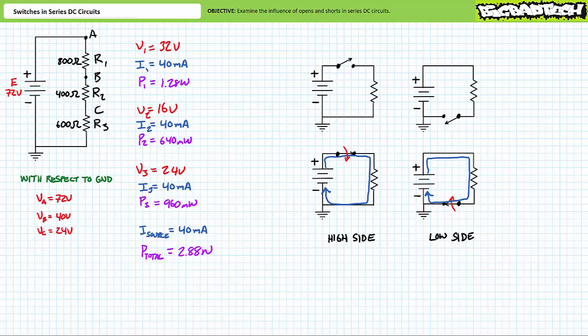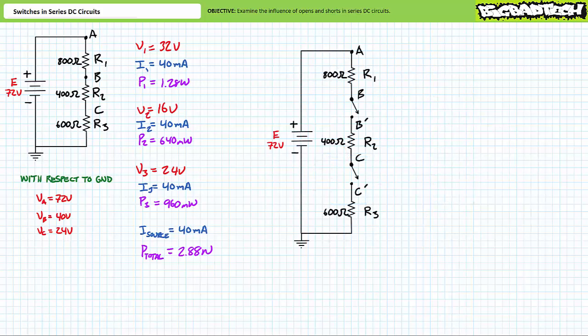I will, however, leave you this clue. Consider an open low-side switch, whereby some errant conductive element accidentally touches the electrical load. What happens? Tune in to the circuit protection element lecture and see if you're right. One last comment about opens in series circuits before we check out shorts. Consider two open switches in this same series circuit. Where does the voltage drop occur?